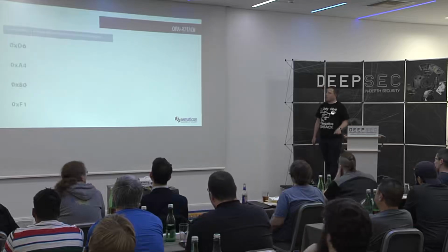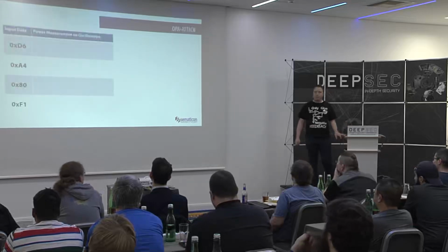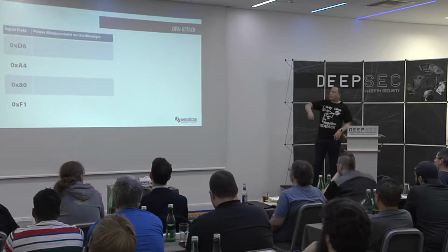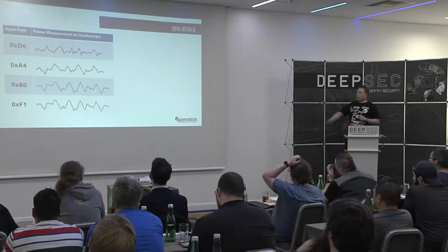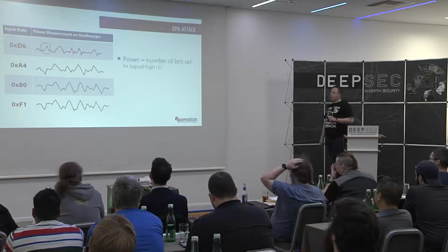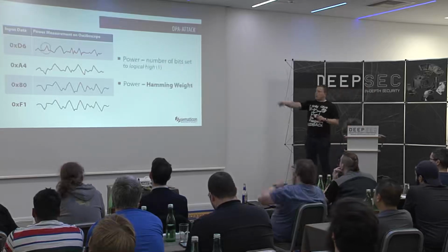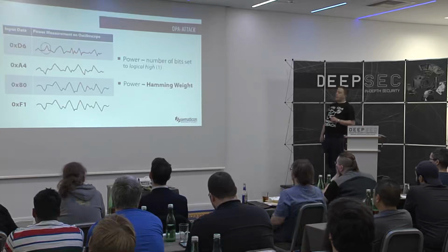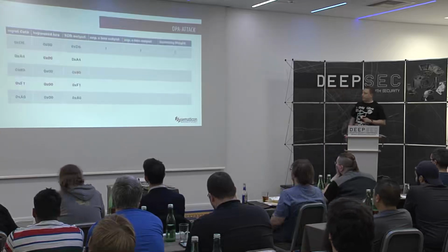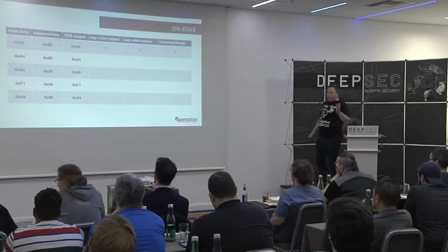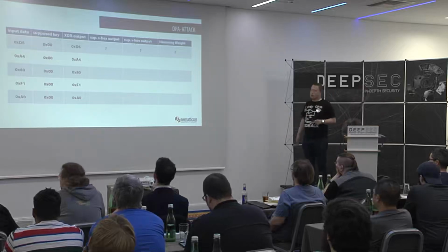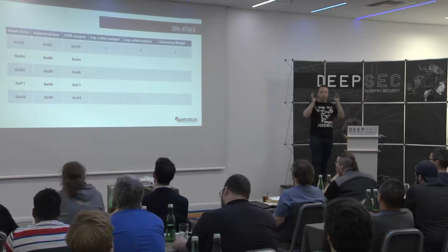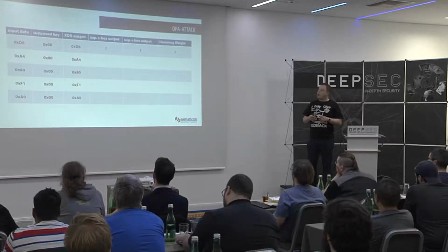That's really cool, because now we can start a DPA attack. We try different input data, get them on an oscilloscope, and we see that for all of the input data, we have different power drawings here. These oscilloscope lines represent what I'm doing here. I'm just taking some input data. I can decide what I use, for example for a bootloader, I use some predefined input, and I suppose a key.